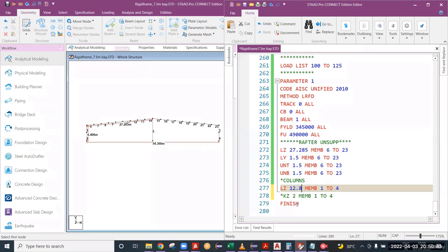One thing you need to know: the tie beam will be connected to the web of the mainframe column, right? Because you are providing the tie beam perpendicular to the screen, it should be connected to the web of the mainframe column. We cannot take these two as separate members in that case. You have to take 6.4 only in that case also.